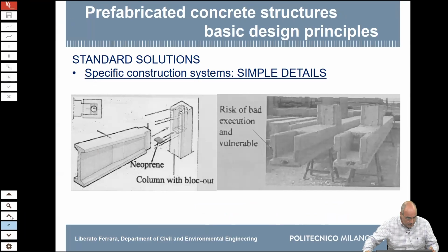Make construction details simple, because they must not only be built, but the precast element must go through transient stages. You have to pick up this beam, you have to lift it up and put it in the stocking yard, and put it on the truck to transport, lift it, put it back, put it on, and so on. There are these transient stages. If the detailing is complicated, it can be an obstacle to this.